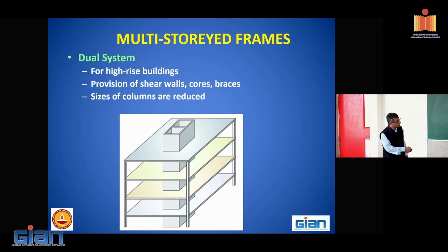In the core, we have this wall system which provides the lateral load resistance, whereas outside we have the frame system which is giving the column-free space for functionality. This is the traditional way the tall buildings in the US were designed. Okay, that core in the middle, column-free space all around.